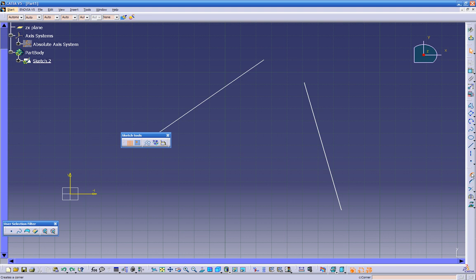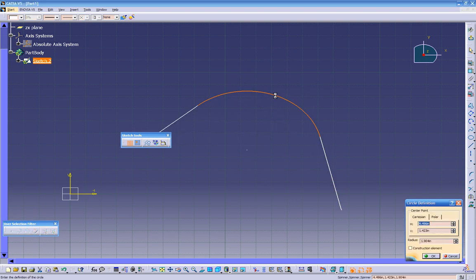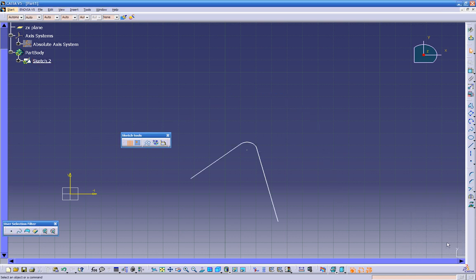on the corner icon. As you see, you have different kind of radiuses you can create. Click on line number 1, number 2. You can put it anywhere you want, but you can go back anytime later on. Just double click on the corner radius, and down here we can change it to 0.250. See, that's the difference. If we do that, it moves the line. So if we do Control Z, we can undo it, and we can do right click